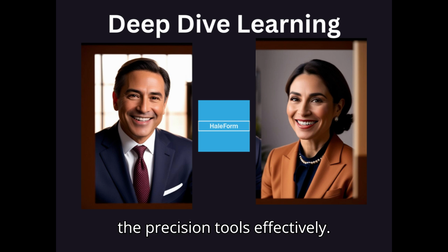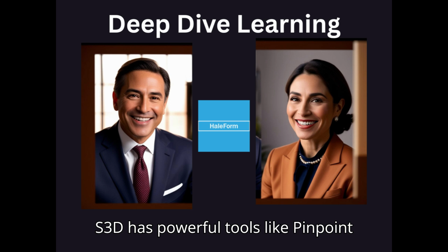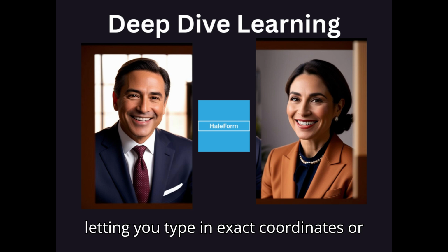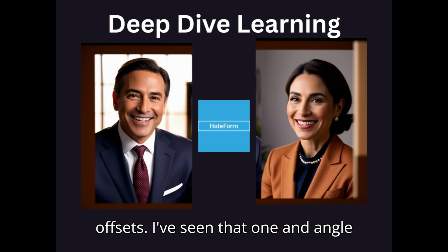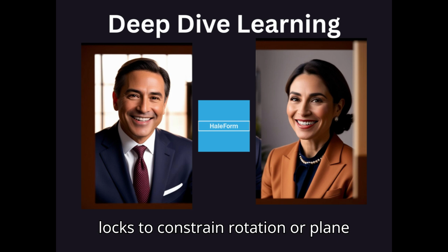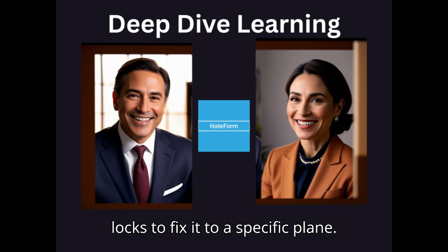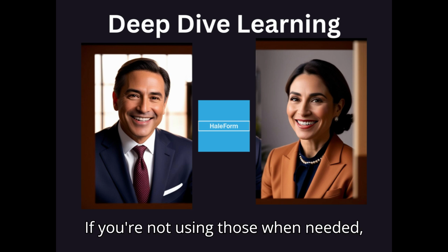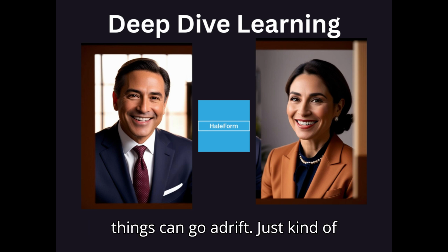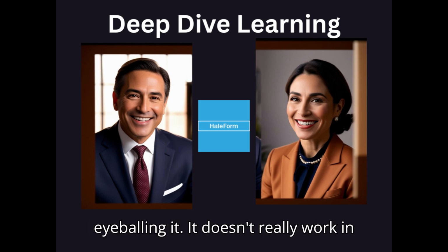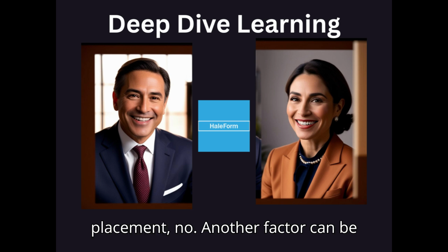Also, not using the precision tools effectively. S3D has powerful tools like pinpoint, letting you type in exact coordinates or offsets. I've seen that one. And angle locks to constrain rotation, or plane locks to fix it to a specific plane. If you're not using those when needed, things can go adrift. Just kind of eyeballing it. It doesn't really work in 3D CAD, does it? Not for precise placement, no.